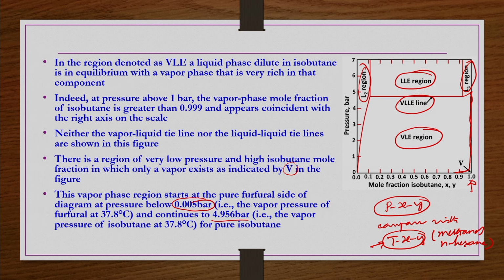So, it is not necessary that we should always have an azeotrope in order to have a VLLE. It is not required. That is, it is not necessary to have an azeotrope in VLE in order to have that VLE coinciding with the LLE before the temperature of the system reaches the upper consolute temperature. That is just one simple case we have taken in the previous lecture and discussed. As already mentioned, different types of complicated phase diagrams may also be possible.